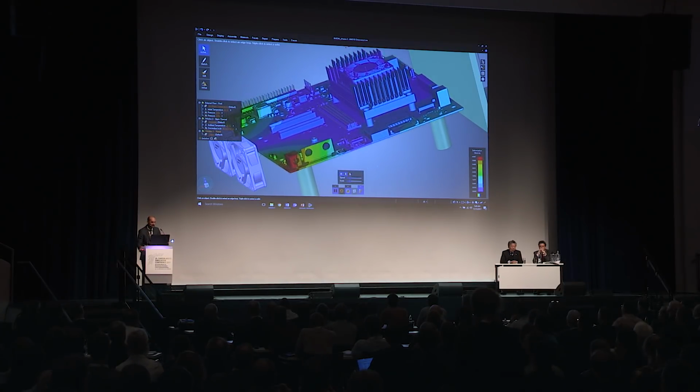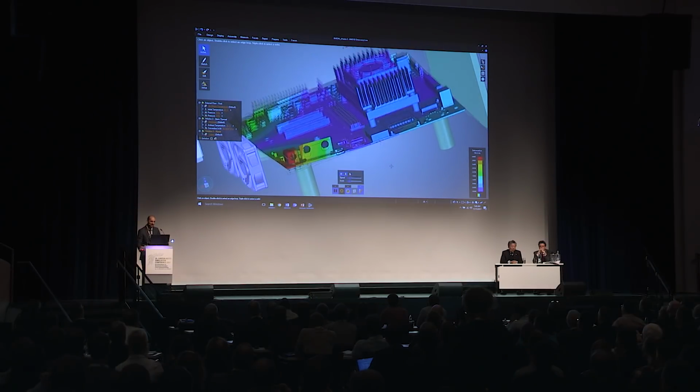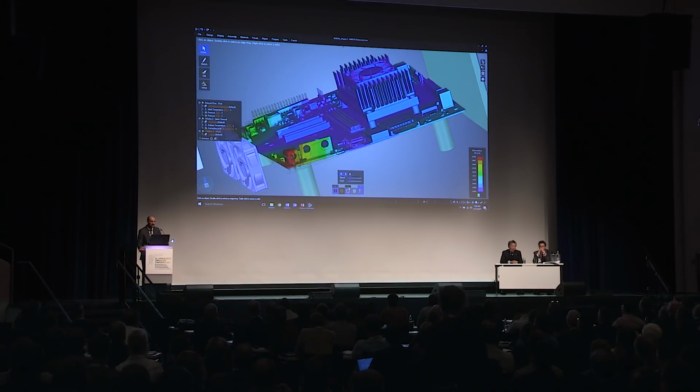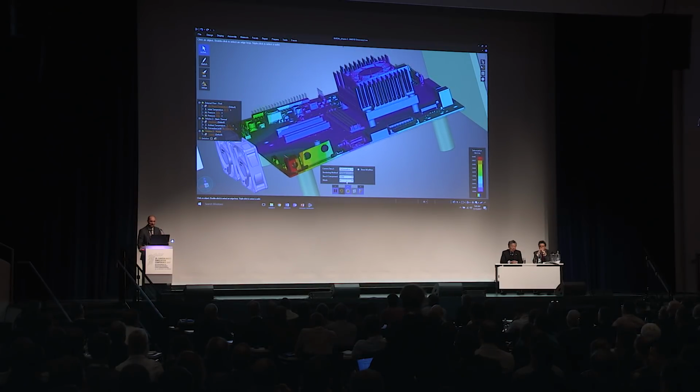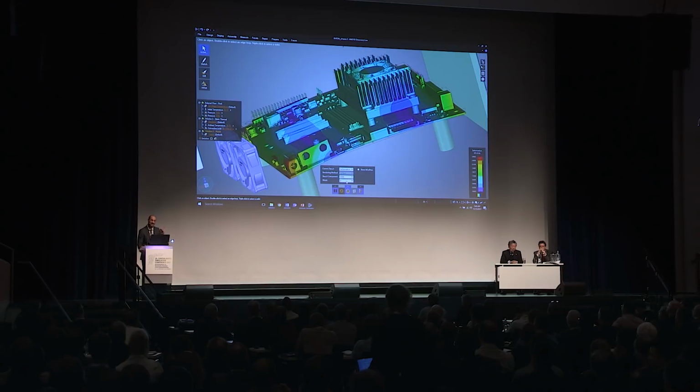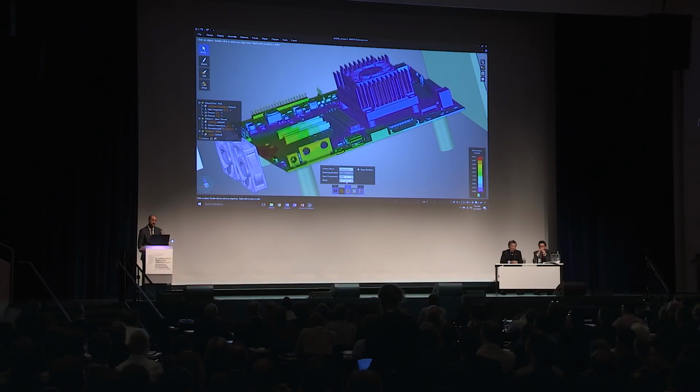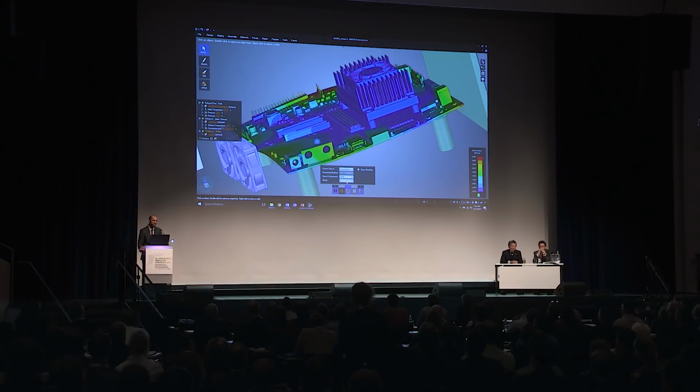So you'll see that that first mode frequency is going down. Maybe to make it a little bit clearer, we'll turn off the animation of color. Now you can see it a little bit better. But as usual, there's more. We didn't just solve for one mode. We solved for multiple modes. Here's the second, the third, fourth, right? All the way up to 6. All at the same time.